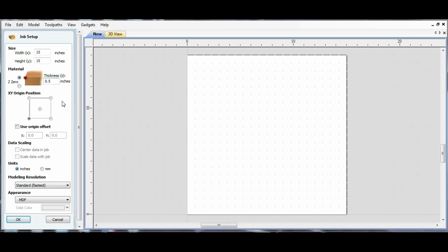It's okay to cut through your actual material into the spoil board. That's why the spoil board's there, and we're going to get into this. Don't worry if you don't understand this. But you don't want to gouge the spoil board. It's expensive. It's a pain in the butt to change.